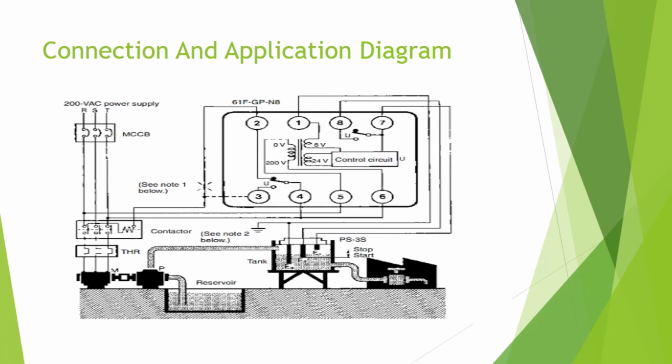Another pin, number 3, is normally open, and number 2 is normally closed. So here is an upper level tank in which 3 electrodes E1, E2 and E3 are used. It depends on your purpose how you choose these 3 levels, or you can just switch the motor on and off with E1 and E3, or E2 and E3.